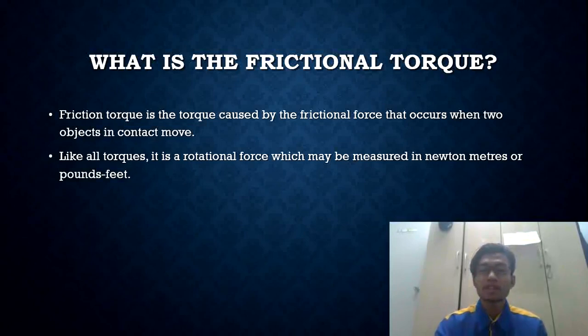So to find the frictional force in the motor, we would have to know the coefficient of friction between each material between the shaft and the motor, and the normal force of the shaft on that material. Measuring the friction of the shaft and bearing could be done by using a force or torque gauge and some knowledge of how to compute moment from force.